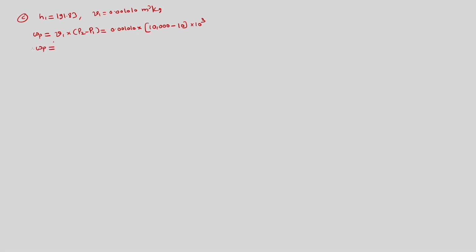So pump work turns out to be 10.08999. So we have H2 is equal to H1 plus pump work, and H2 over here will be 201.92 kilojoule per kg.